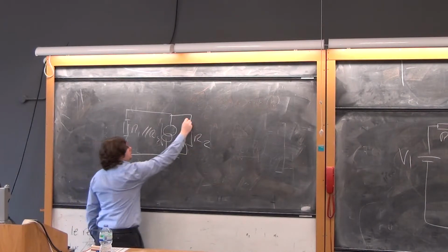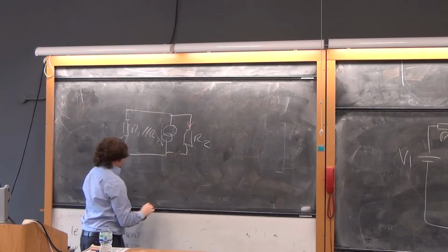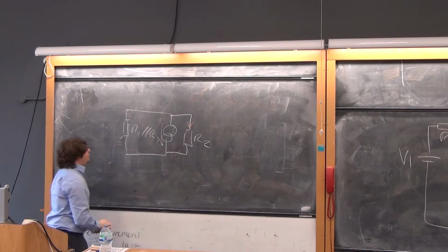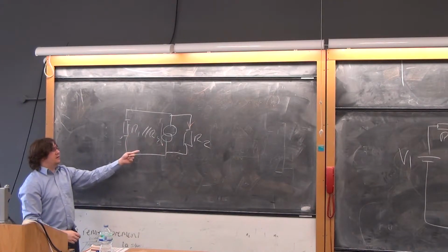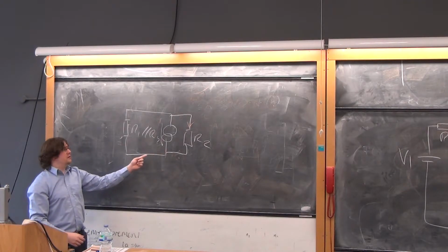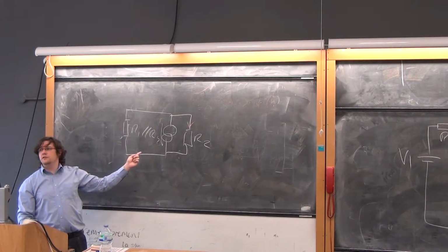So if you prefer, you can just draw it as that one there, which is the same thing, makes no difference. In which case, you know how much current, you know what the parallel of these two is, and it's shared out according to the lowest resistance gets the biggest current.